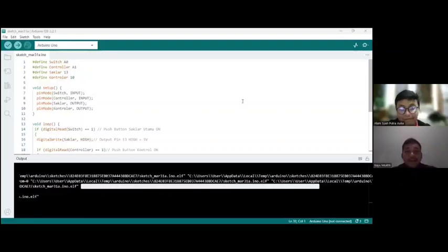Next, define the pin mode, which will be used to decide input or output. Normally, input mode on the switch 1 and switch 2 pins, and output mode on pin 1 and pin 2. After that, we use an if-else loop. If switch 1 is low and switch 2 is low, then pin 1 and pin 2 are low.